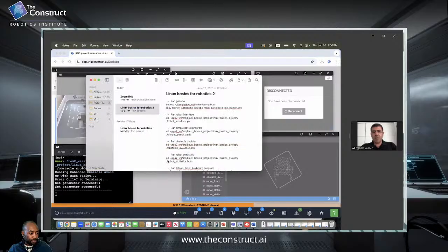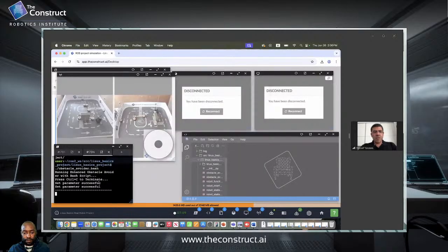In addition to that, we can run the robot statistics as well. We can see now the sensor robot, and we can see the different statuses of the robot from the front to the right. Let's say front, there is a front left, there is a front right. In addition to that, we can see left and right, etc., with the distances that the sensors are reflecting to us. Now we see the threshold as 0.3, which is 30 centimeters.